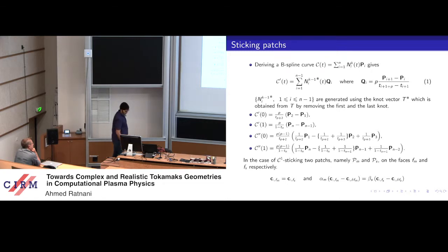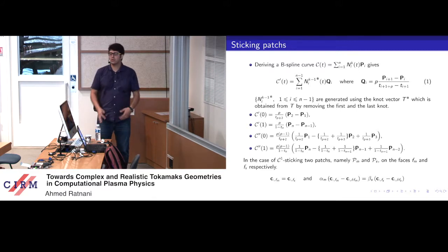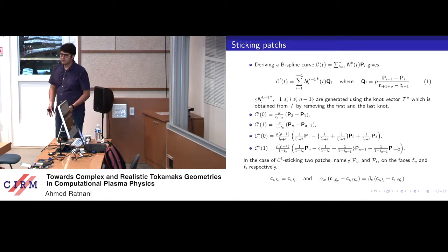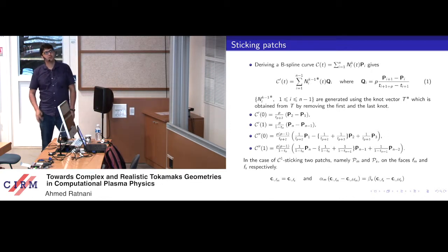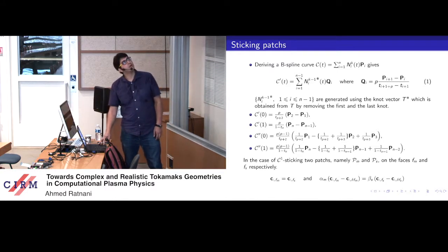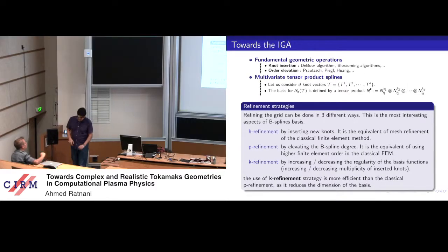Okay, so B-splines are polynomials of degree equal to the order minus 1. They are polynomials with the smallest support for what we call the Schoenberg space. They have also linear independence, partition of unity, which is very important for the completeness of our finite element space.